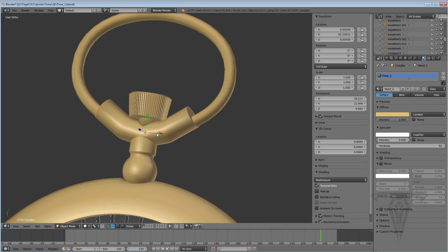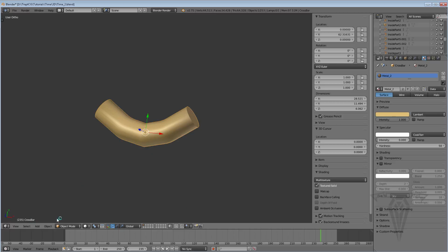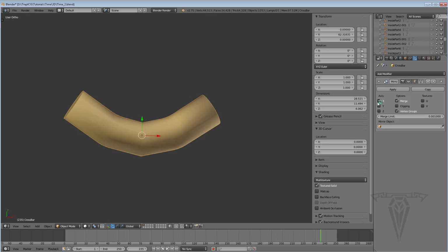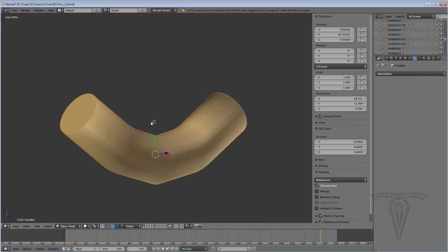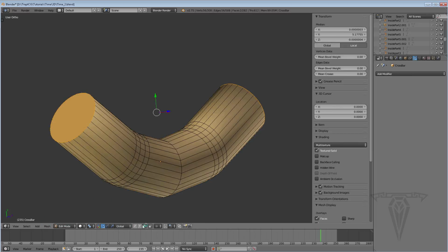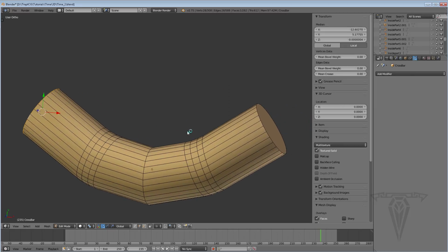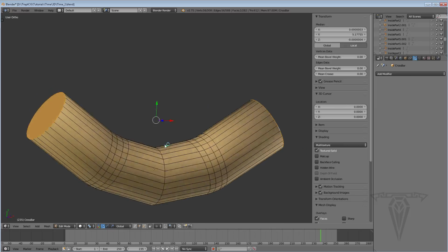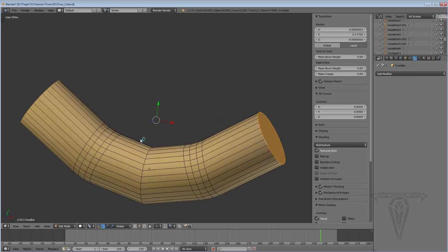I'm going to do Shift-H. Otherwise, go to Object, View, etc. And this object has a modifier applied. So let's go ahead and actually apply it so it's one solid object. All right. And there's one more thing I want to do. I don't like these hard edges that are here. So I'm going to go into Tab, Edit mode, go to Edge, and select this edge. Hold down Shift and Alt, click on this edge. Again, I'm doing loop selections. Shift allows me to add multiple selections.